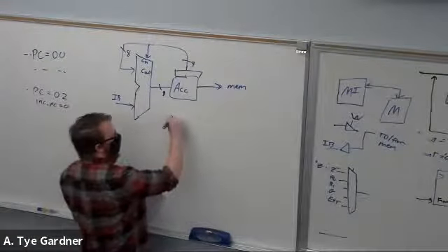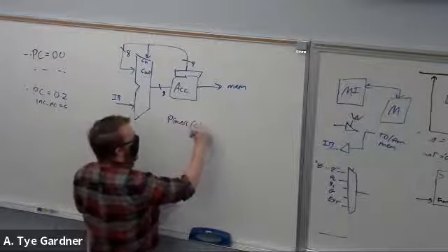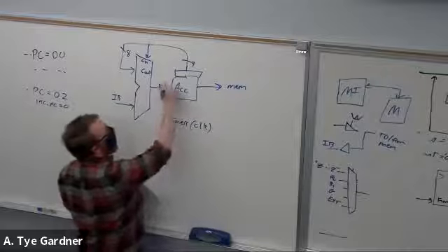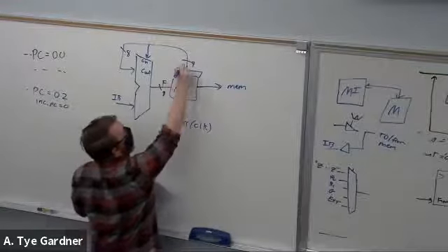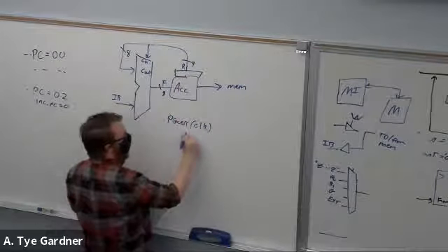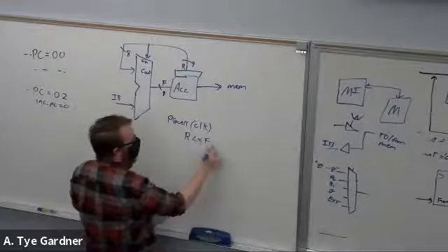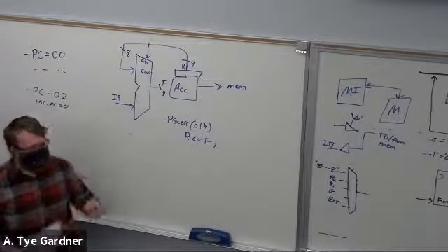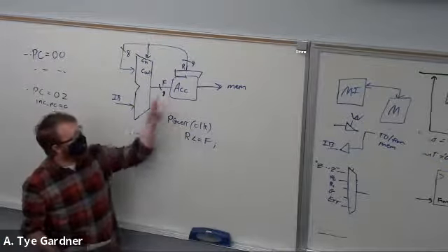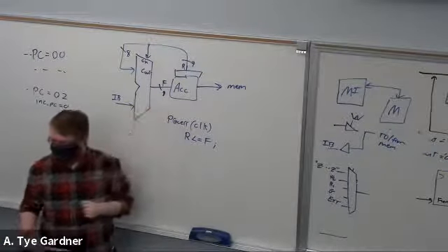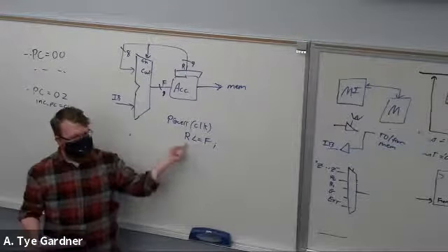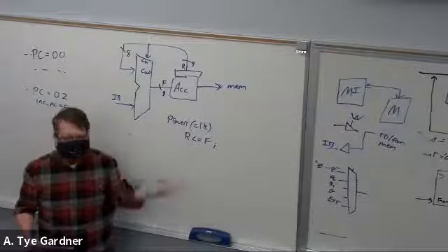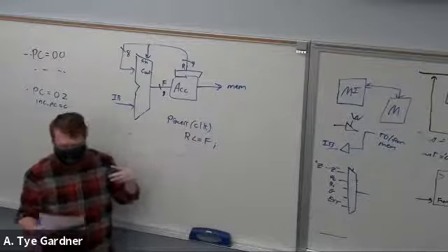Also, you could just do something like a process on the clock. If this is F and this is R, then you would just say, each clock cycle assign R to whatever's on F. This implements a register. So you don't have to write the D flip-flops. You can just do this. Okay.